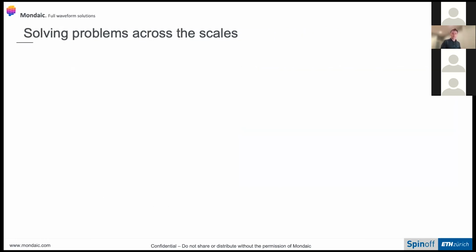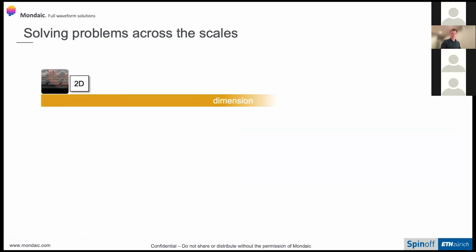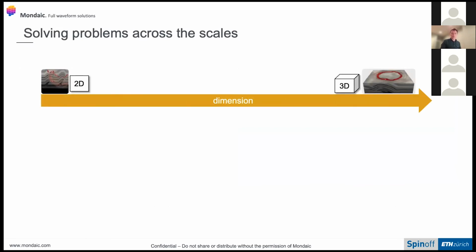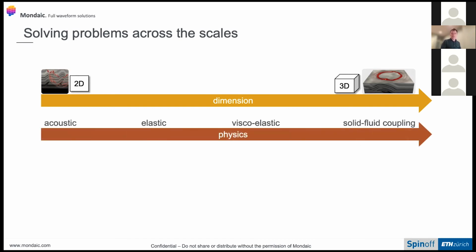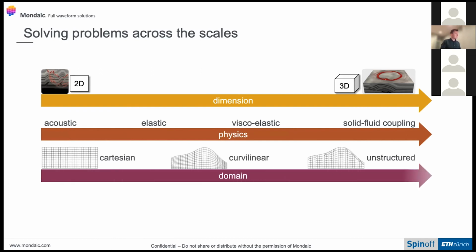So in the end, Salvus is a code for multi-scale full waveform modeling and inversion. We're really trying to bring all applications which can be studied by waves together under a consistent and easy to use interface. To summarize, Salvus supports 2 and 3D visco-acoustic and elastic physics, including full anisotropy in the elastic case in 2 and 3D. It includes proper modeling of the fluid-solid condition in coupled domains as well. And through a custom built meshing toolbox, we support unstructured domains of graded complexity.